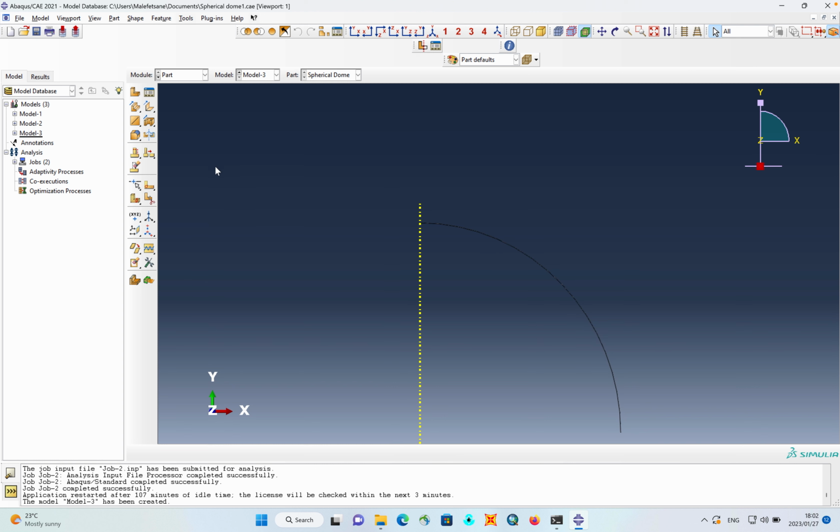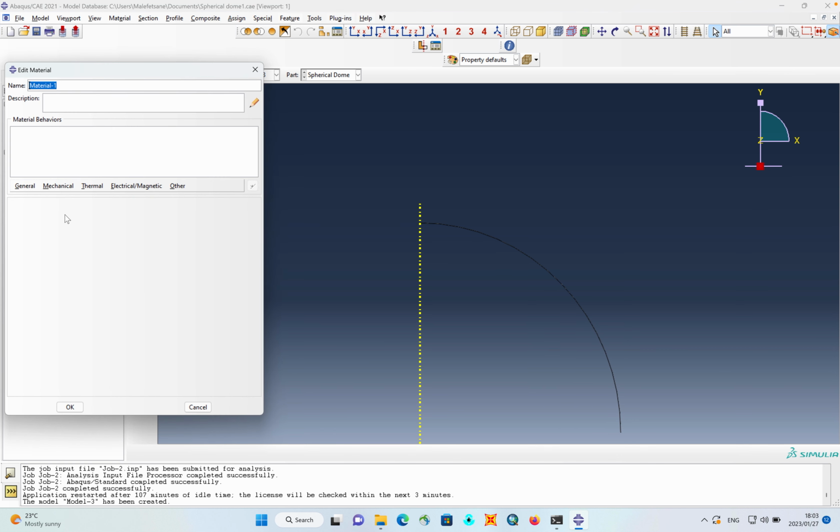Okay, so now let's assign our material properties. If you remember in the previous video, I did say we should make it concrete, but as I was reading the question, I thought, you know what, let's just stick to metal. So we use steel materials. It's an elastic analysis. We ignored the self-weight in that previous question, so we're not going to include the self-weight here as well.